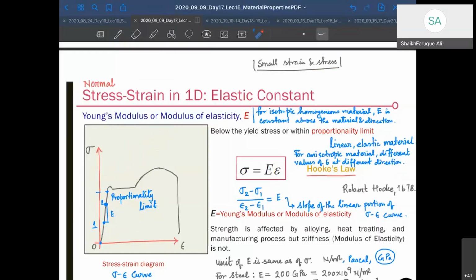If the material is ductile, it's going to show up a relationship. The relationship is, as we increase the strain in the material, the stress goes up. This is the stress axis, this is the strain axis, and it will show a very nice linear relationship. It will go up like this, and after a certain strain, it will have a kink here, and then there will be a flat region, flat with respect to stress, and then it will again grow up, go up, go to a maximum value, and then the value will start falling, and suddenly at this point it will show a complete failure, and it will fall like this.